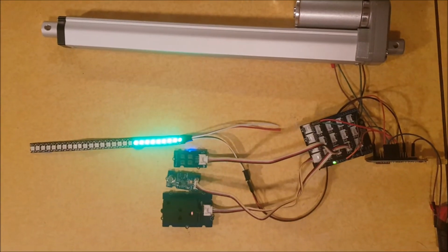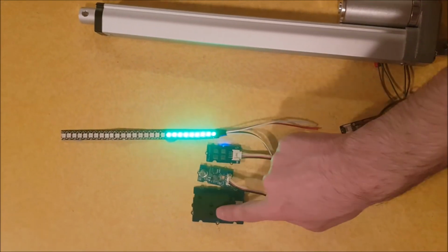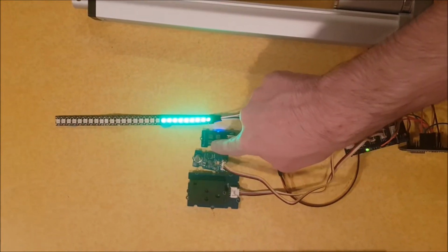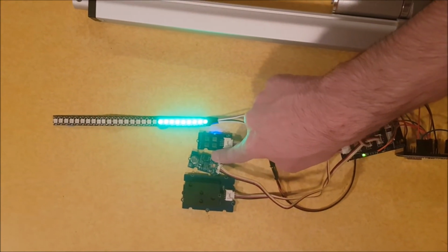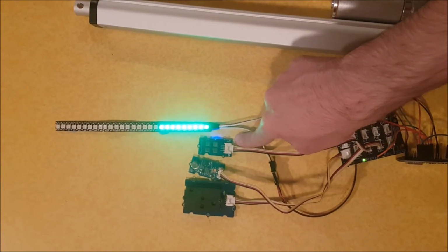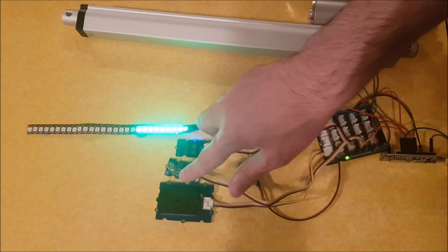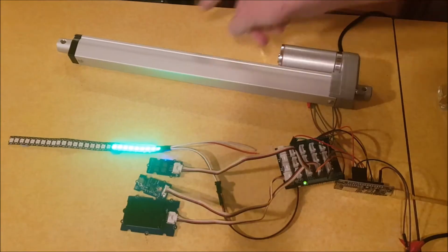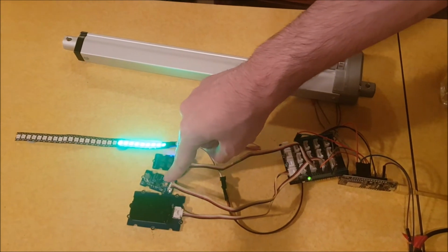Using the hardware that I just talked about, here you can see the SCD30, which I'm using to measure temperature and humidity, the air quality sensor, which is highly sensitive to smoke and alcohol, and the multi-channel sensor, which we're using to measure carbon monoxide. As just explained, the air quality sensor is highly sensitive to alcohol and smoke. The LED strip is connected to the air quality sensor.